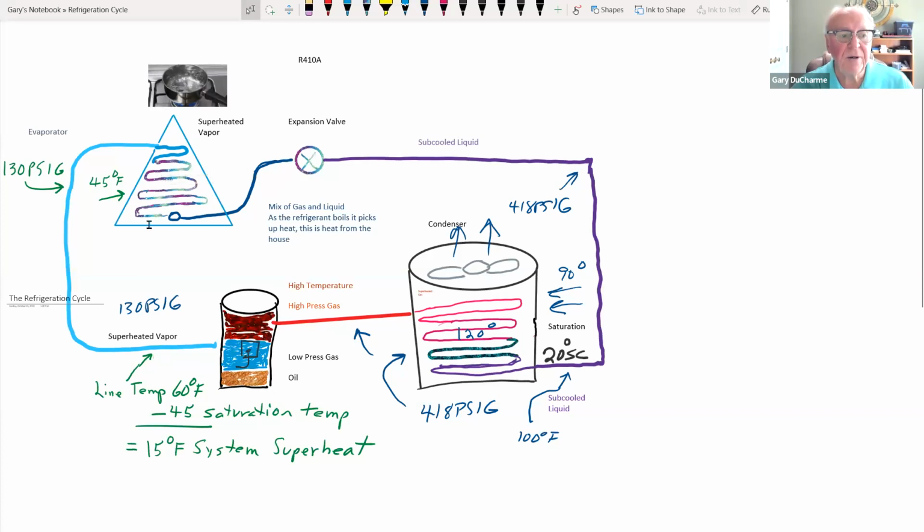And this evaporator that we see here is typically always inside of the air handler in the house or a furnace in the house. It's always going to be indoors. Your condenser is always going to be outdoors. So assume that this evaporator here is sitting in a fan coil or a furnace in your basement or your attic. And we're just talking about the evaporator here and not the fan coil as much. We do know that the fan coil brings air from the room across this evaporator and goes out into the room as conditioned air. So just assume that is happening here.